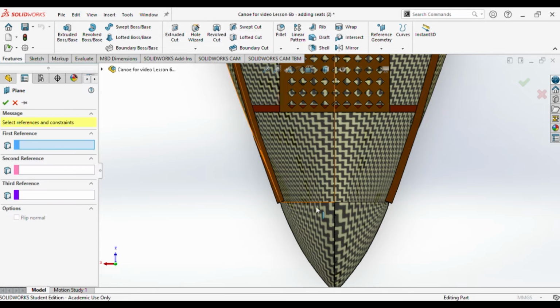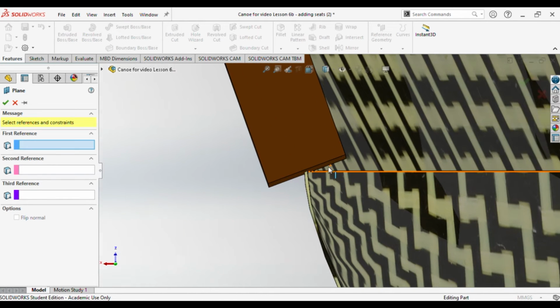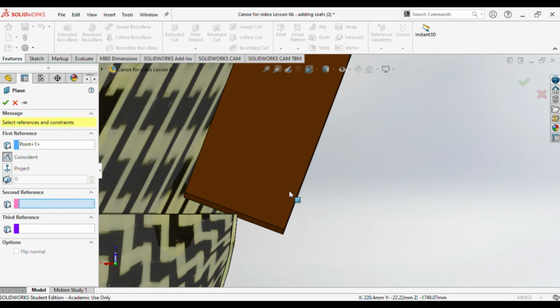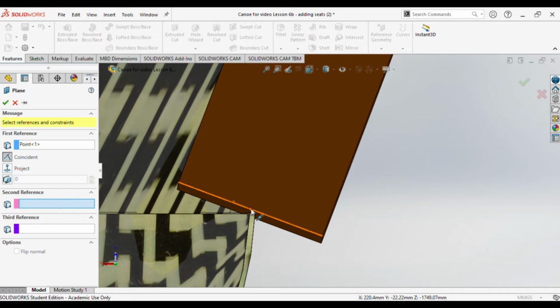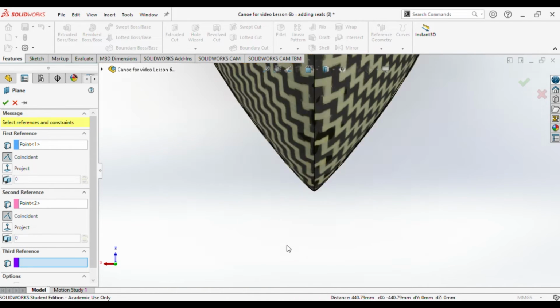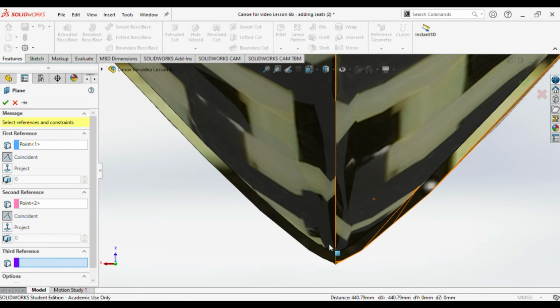We could try to draw it on the top plane, and then project it onto the top surface of the canoe shell using a wrap, emboss command, but we'd be blocked from selecting the surface, and we'd get an error message reminding us that the wrap tool only works on planar, cylindrical, conical, extruded, or revolved surfaces. If we tried to use a sweep like we did for the rails, we'd find that something about how the ends of the canoe were drawn prevents us from selecting the top edge as a path.